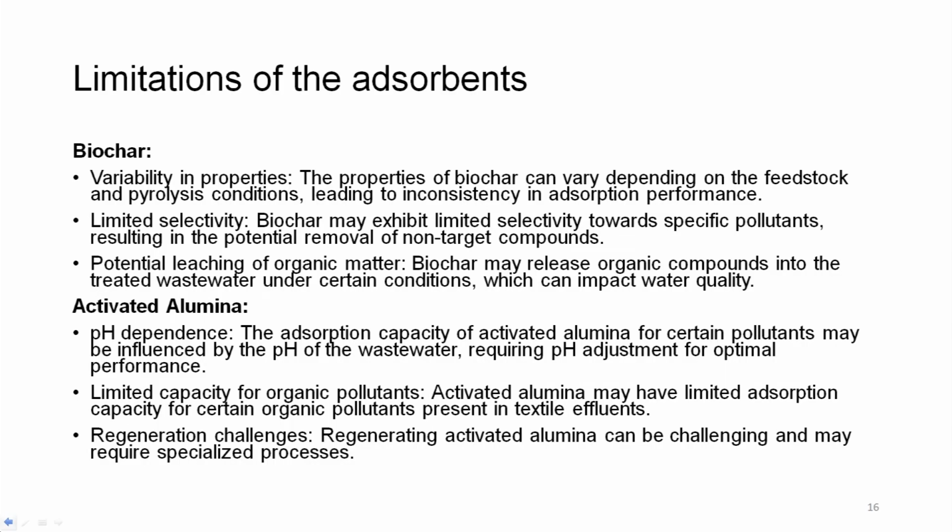Activated alumina. pH dependence. The adsorption capacity of activated alumina for certain pollutants may be influenced by the pH of the wastewater, requiring pH adjustment for optimal performance. Limited capacity for organic pollutants. Activated alumina may have limited adsorption capacity for certain organic pollutants present in the textile effluent. Regeneration challenges. Regenerating activated alumina can be challenging and may require specialized processes.